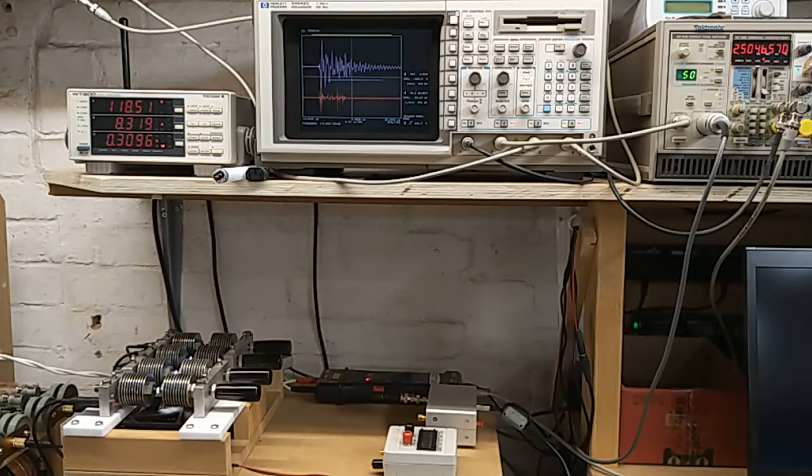We can see the burst waveforms on the oscilloscope. We're around about 300 watts, which is the same power we were running the vacuum tube oscillator at, or at least the input power to the high voltage transformers. And we can see here we are measuring 2.4 megahertz, and it's quite stable. So that gives us an idea of the central, the strongest central resonant point for the current setup of the system.